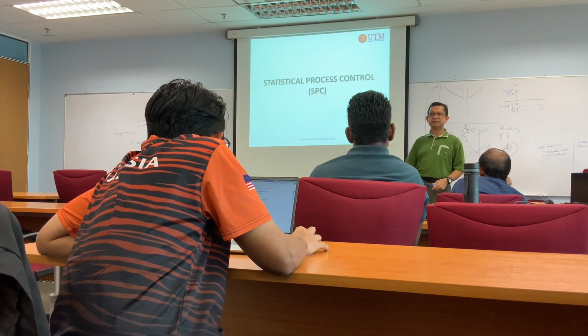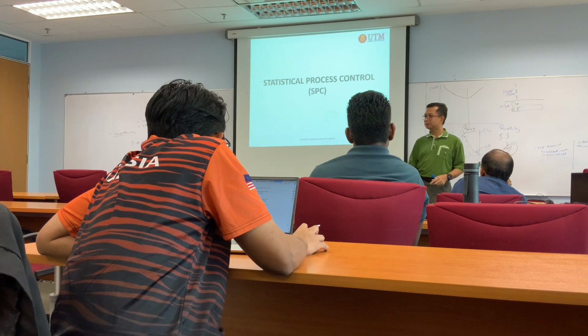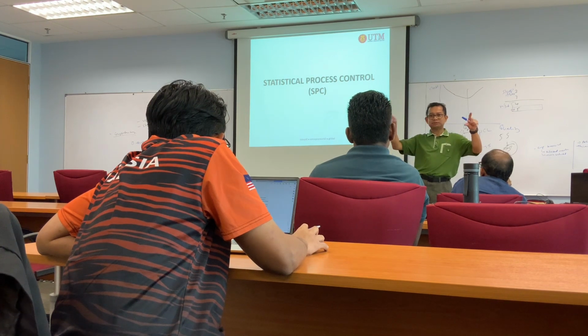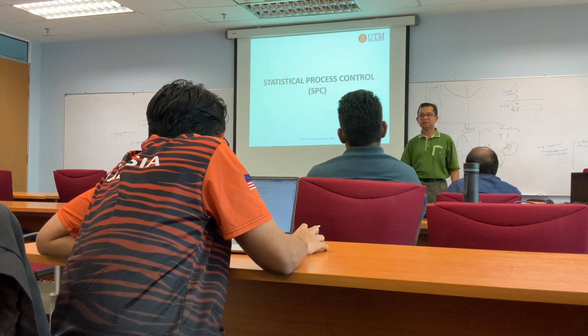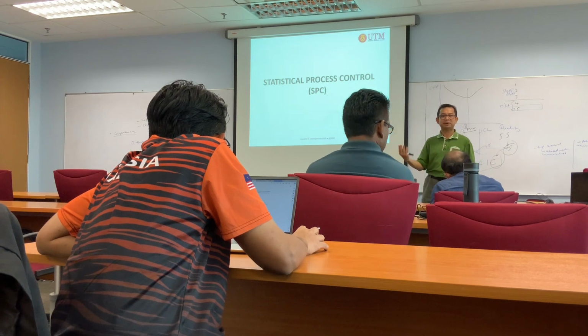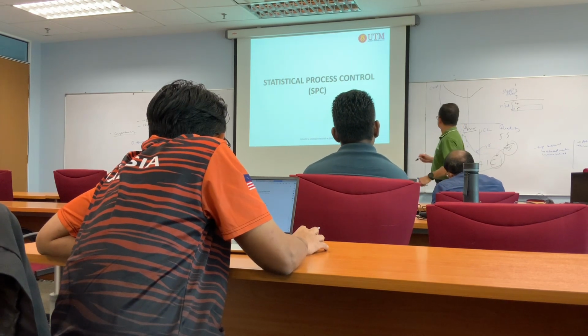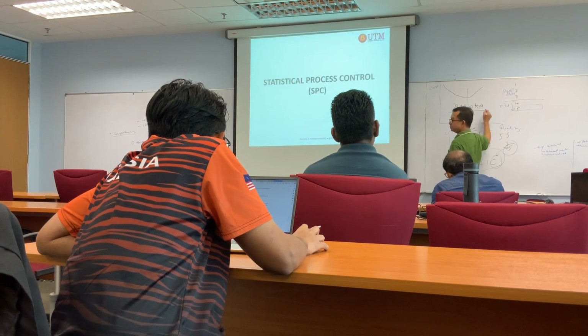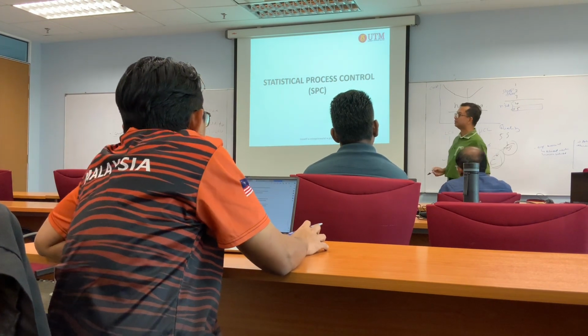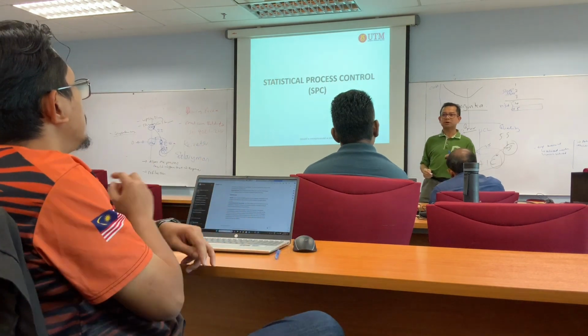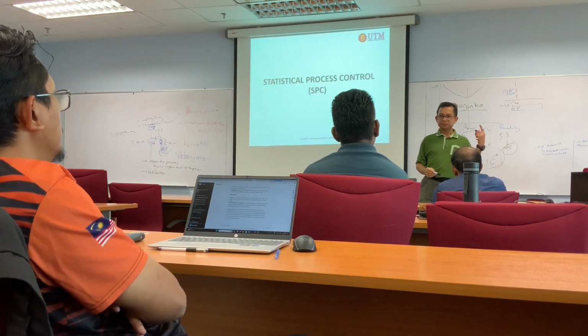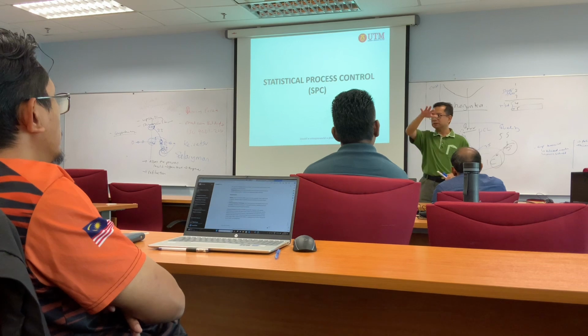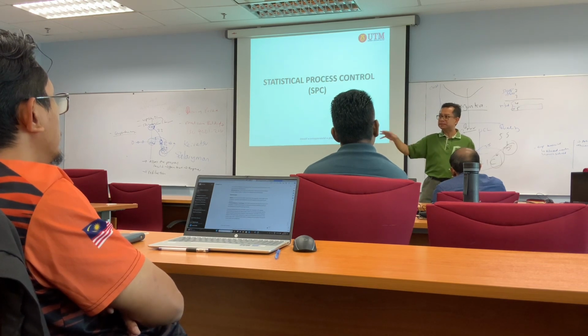I did the time study, I did the Yamazumi. You know Yamazumi? You will learn in the lean subject, Yamazumi, how to do the line balancing and so on. Using Heijunka, Japanese we call it Heijunka. Because we want to avoid the muri, mura. We want to eliminate mura, so we do the Heijunka balancing, line balancing.